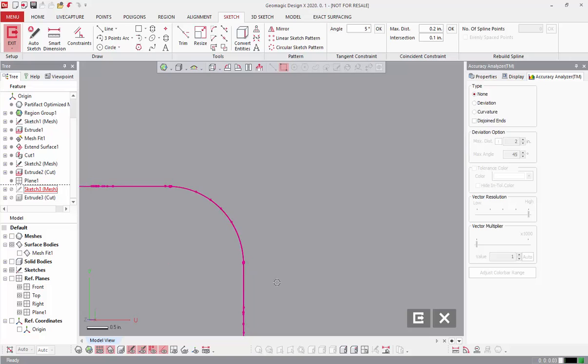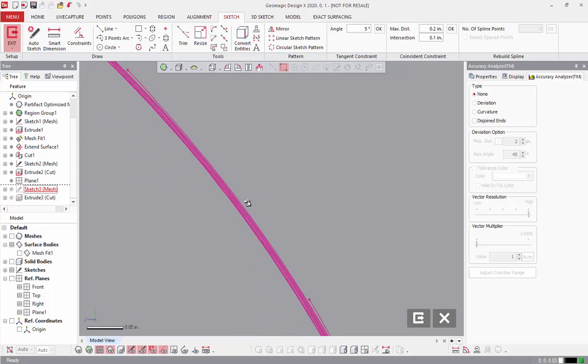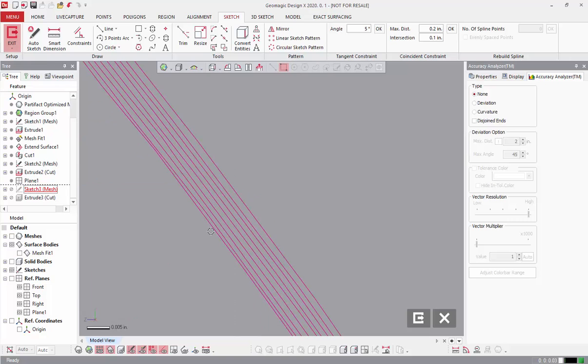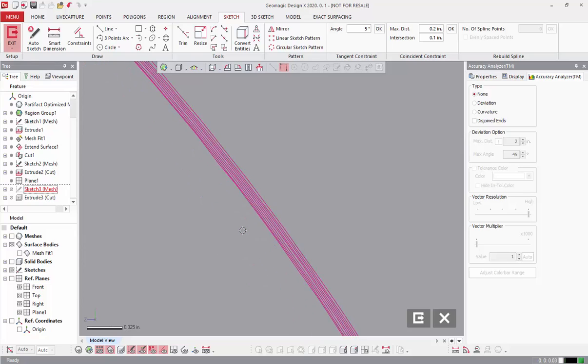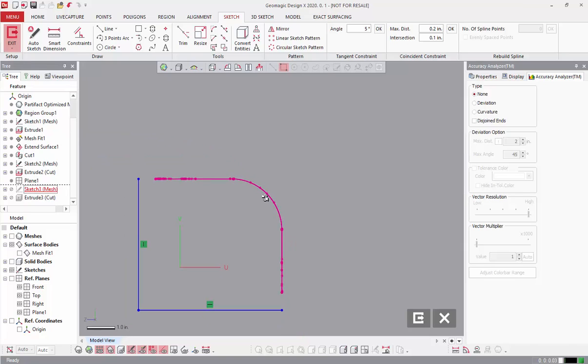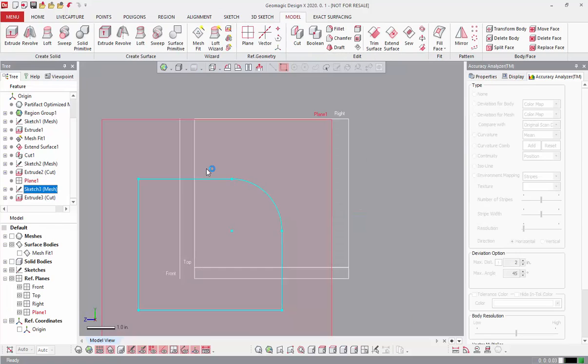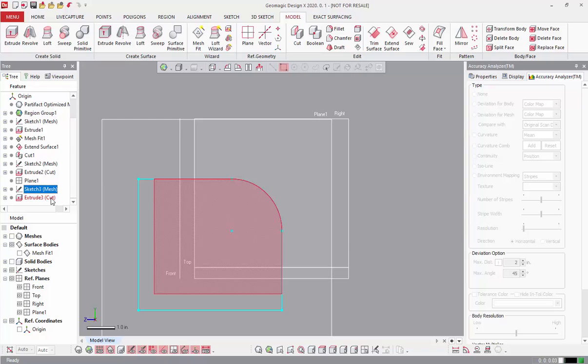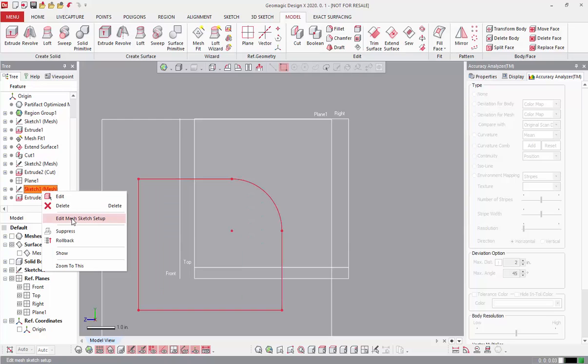What we'll see is a thick line, and if we zoom in further and further, we'll see 10 of these cross sections all really close to one another. I'm zoomed in so that this is about 5 thou here. So there's about 5 thou of variation between all of these sections as they exist on that cross section plane. What average section does is it averages those 10 sections, right? It takes out any variability if this isn't a purely vertical wall shape or anything else.